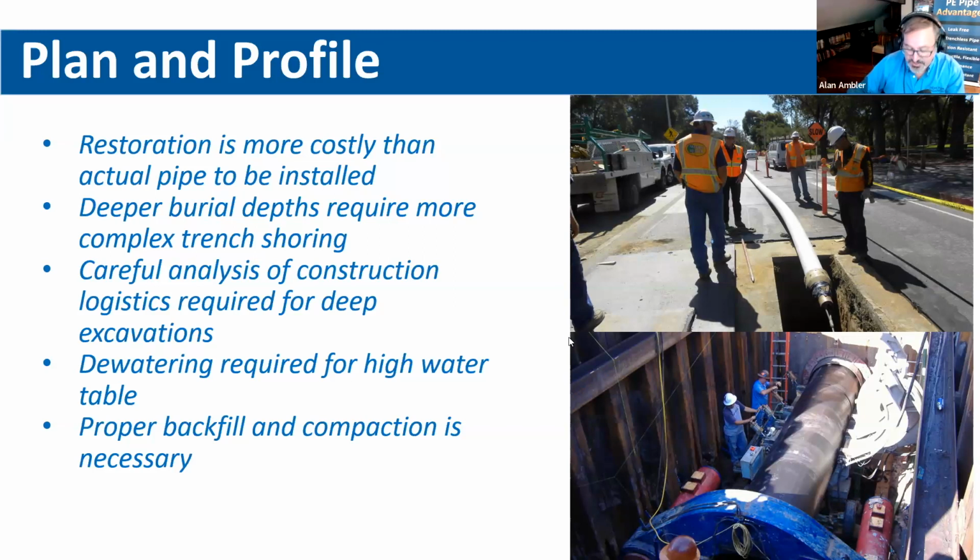But you can install high-density polyethylene, your contractor can, in many of the same manners as to which you'd install segmental pipe. And when we start thinking about productivity on the back end and the front end, we'll be able to get more shoring devices, get more areas, and be able to open up and get in there a lot quicker. Go ahead, Richard.